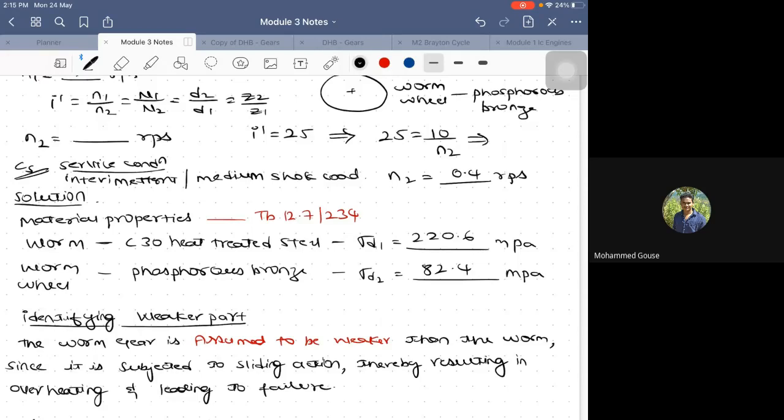Now, all of you just look into your data handbook. Do I get something through which I can calculate my center distance? Look for an expression. Not necessarily A equal to something, but something like power is equal to something of A. I know the value of power, which is 30 kilowatt. Through power, I can calculate the value of A. Is there any formula that would facilitate this? Please check your data handbook and let me know.